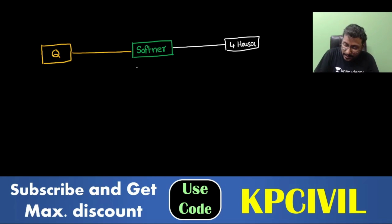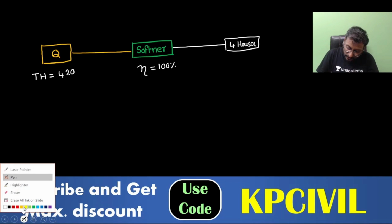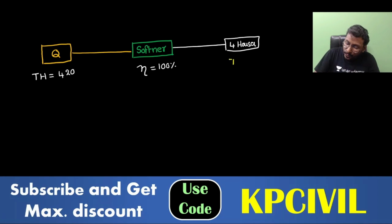The efficiency of the softener is given as 100%. What is the starting total hardness? Starting total hardness is 420. But the 4 houses have received water with a hardness of 75. How is efficiency 100%? But 4 houses receive not 0 total hardness, but 75 total hardness.